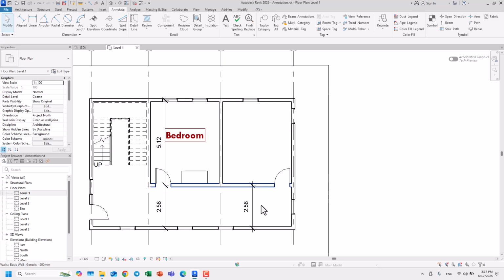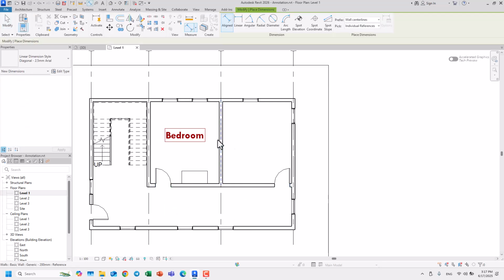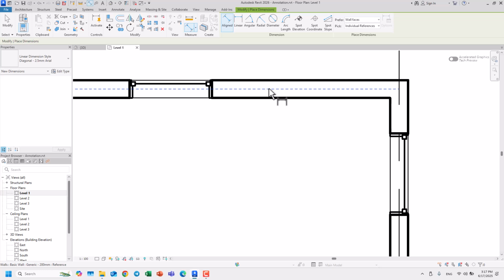So okay, let's delete this, and delete this. DI again. Let's go to the other ones, wall faces. This was wall center line. It takes it from the center line. This is not what we want. We'll go to the wall faces. Wall faces which will take the face of this. Still we have the option of center line, but we will go with the faces.